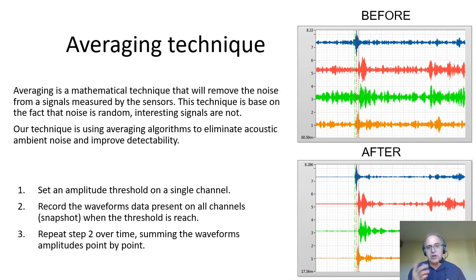But what we're looking for is always the same thing, same place, same shape over time. It's PD, because the PD is not moving. We are in one position, the PD stays at the same position. So we get the same thing over and over and over, but the noise is totally random, and we are capturing the same thing over cycle.